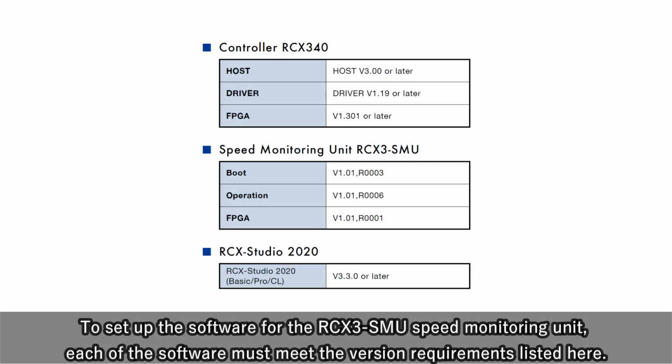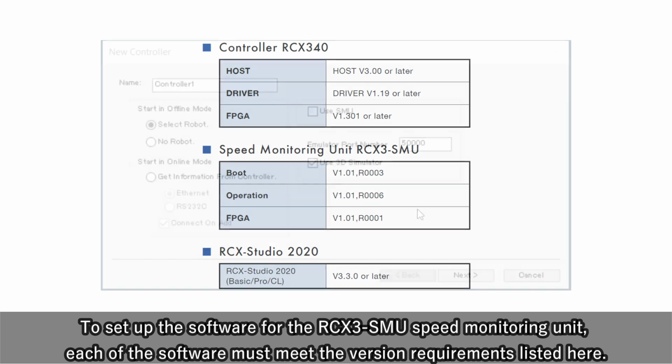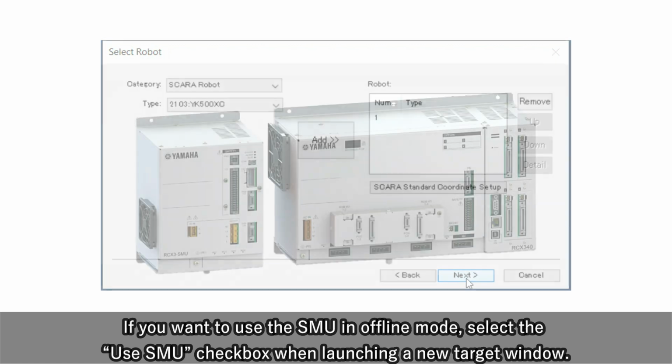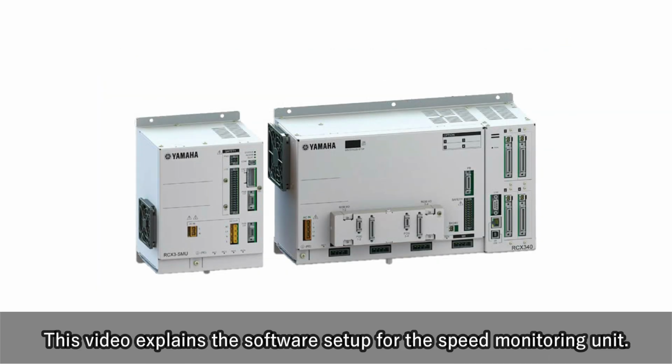To set up the software for the RCX3-SMU speed monitoring unit, each of the software must meet the version requirements listed here. If you want to use the SMU in offline mode, select the Use SMU checkbox when launching a new target window. This video explains the software setup for the speed monitoring unit.